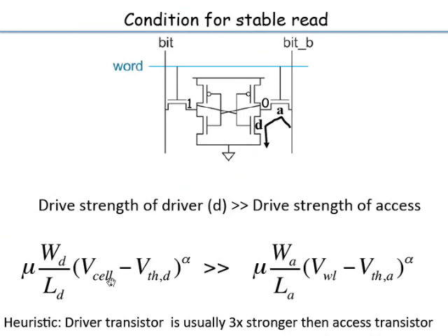Different supply voltages. What supply voltage will you use for the cell? Higher than that of the word line. Now the word line, remember, will finally have one simple inverter driving it. So the supply voltage to that inverter is what is VWL. Okay, so if you reduce VWL relative to V cell, again you can weaken this. Okay, what else can you do?